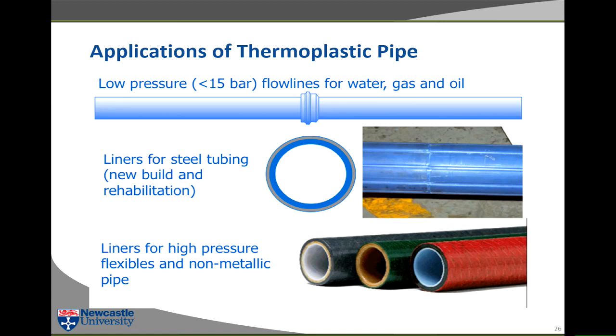So if you're using the liner for a pipe which has either natural gas or crude oil with a gaseous component in it, the gas under high pressure can diffuse through the thermoplastic. Thermoplastics allow gas to diffuse slowly, but it happens. So if one of these pipes has been in use for a long time, then the pressure of the gas at the interface between the thermoplastic liner and the pipe wall will be equal to the pressure of the gas inside the pipe, which is not a problem unless you depressurize the pipe.